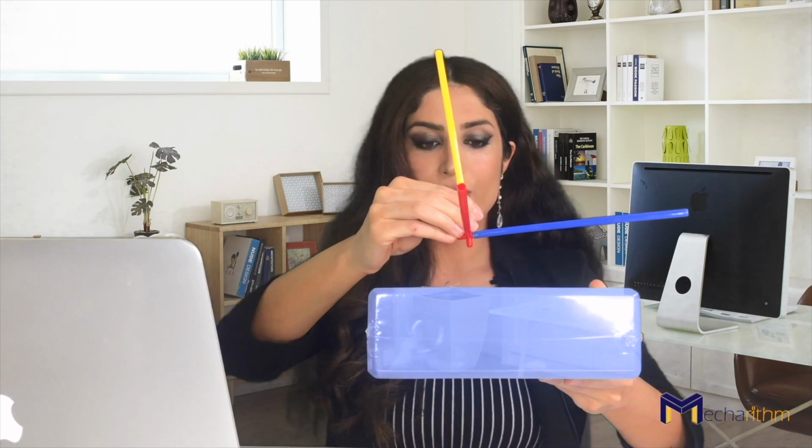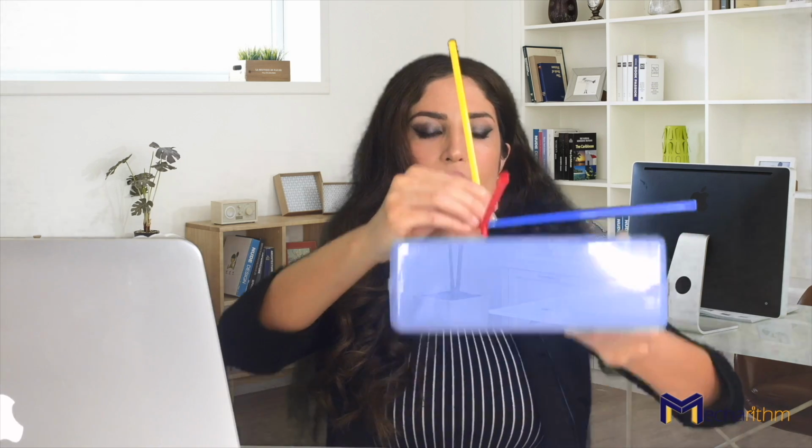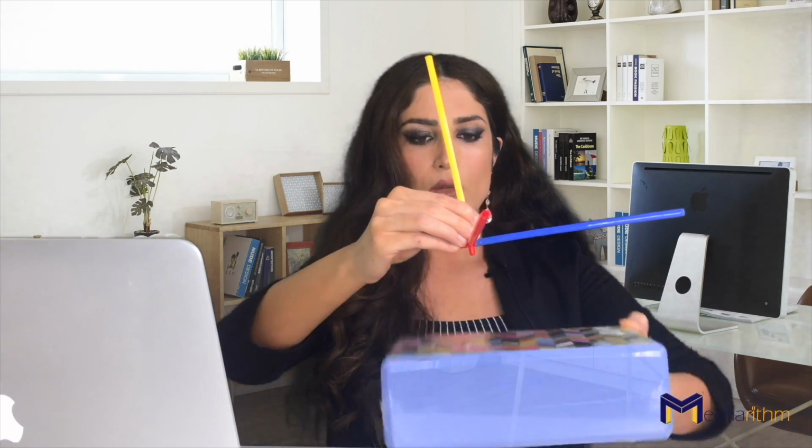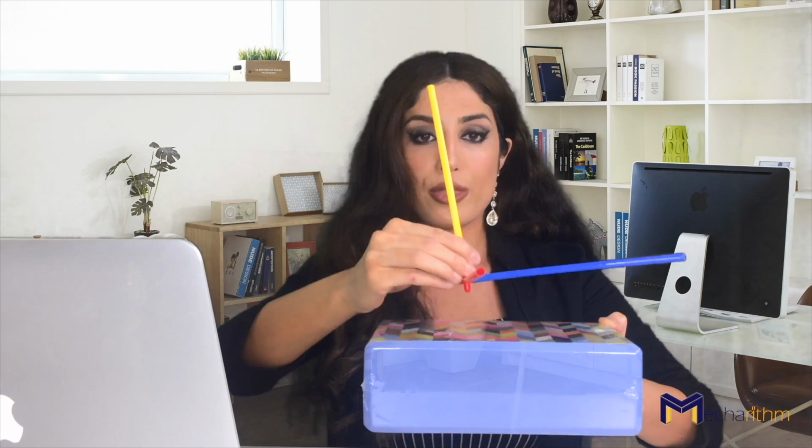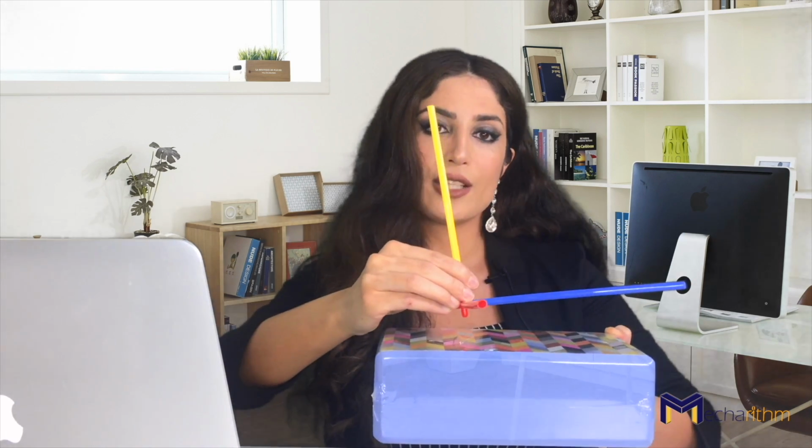A rigid body in 3D space has 6 degrees of freedom. So suppose that this is X coordinate, Y coordinate, and Z coordinate. So the rigid body has 6 degrees of freedom. The motion along the X-axis, the motion along the Y-axis, and the motion along the Z-axis. These are 3 translational degrees of freedom. It also has 3 rotational degrees of freedom. Rotation around the X, rotation around the Y, and rotation around the Z-axis. So overall, it has 6 degrees of freedom, 3 for orientation, and 3 for position.